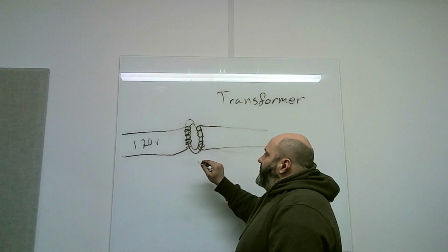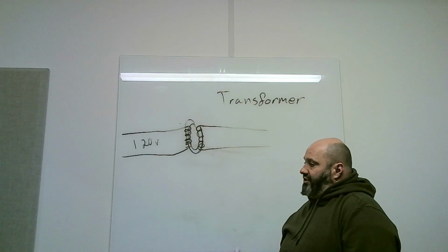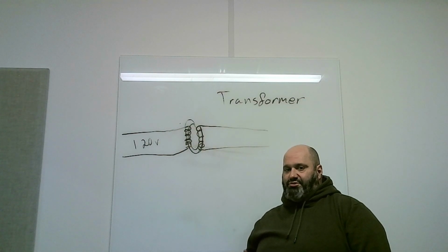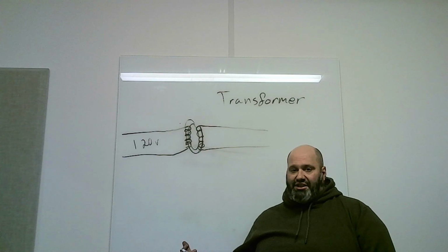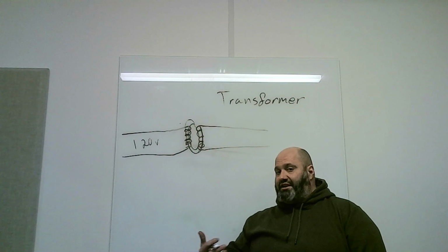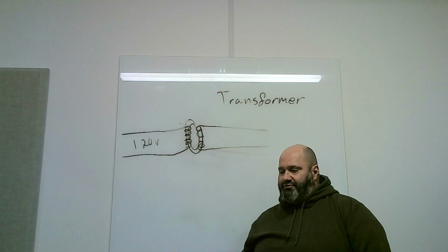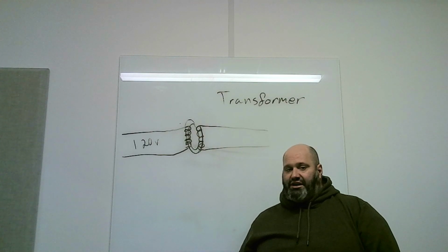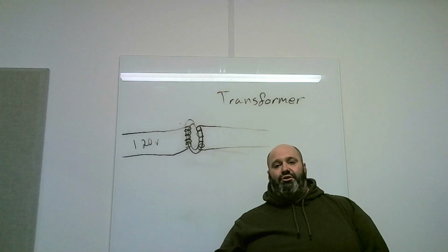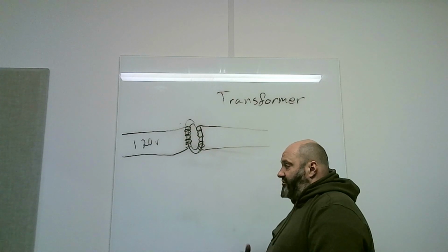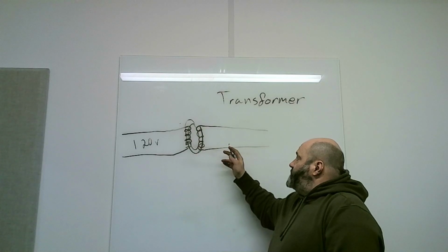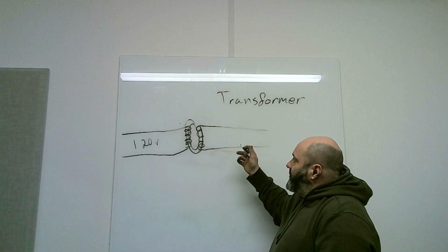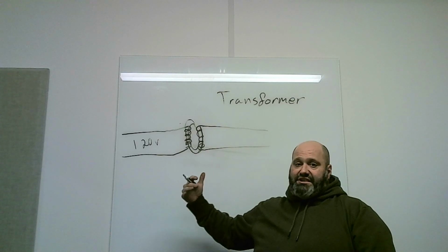Well, in order to power things like controls, or to have a control signal sent through a safety device, like say a limit switch, or for your control board to be able to detect that, let's say, your pressure switch has closed, indicating the inducer motor is on in a gas furnace, you need to have 24 volts, at least in most residential systems.